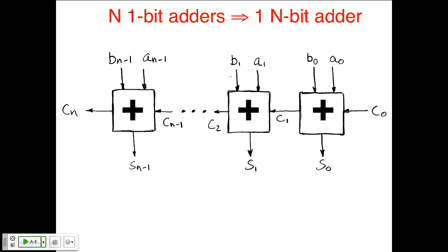It slowly propagates through the circuit. And finally, at some point in time, the whole adder, all the output bits will be correct according to those input bits. Okay, it's a combinational circuit. Right, the signals just propagate through as a wave through this whole array of gates. And that's how you build a 32-bit adder.